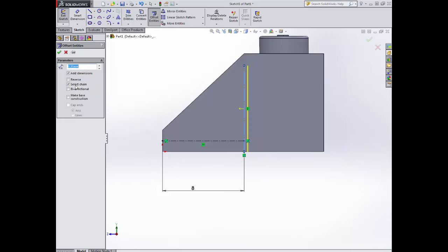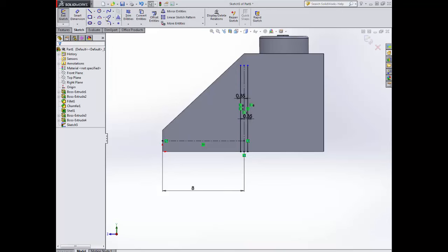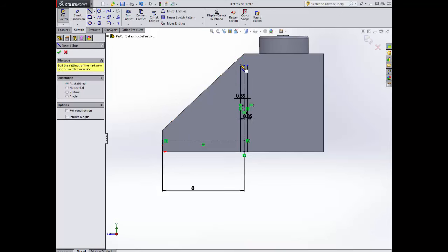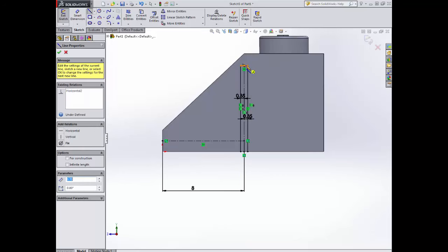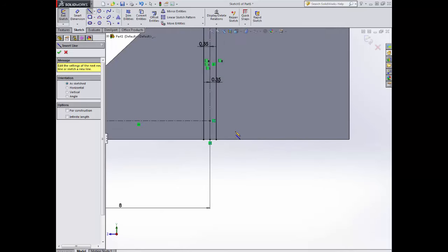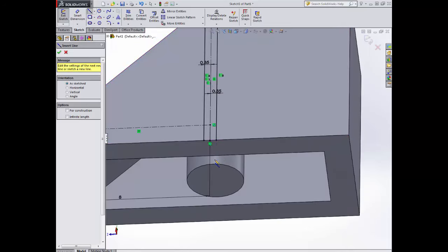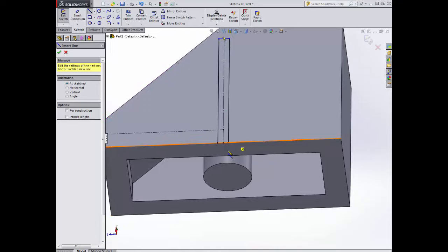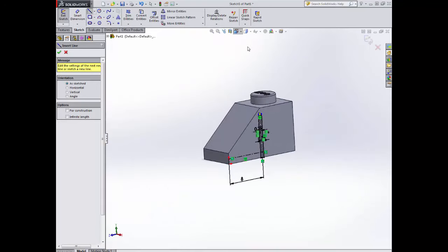That gives me one side. I'm going to go bidirectional. So bidirectional, click that, and you can see the preview shows me the 2 yellow lines. Green tick that, and then what I can then do is close this off. SolidWorks only works on an island principle, so that means that your lines all have to meet up around the edge. If they don't, it won't understand what you want to do. So I'm going to zoom in here, just checking that that's in the middle. Happy with that.